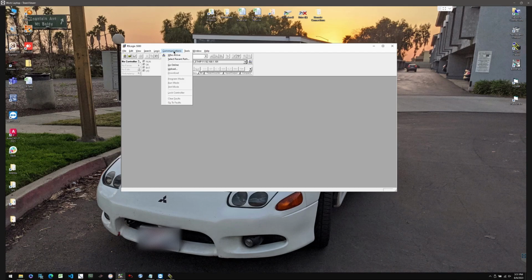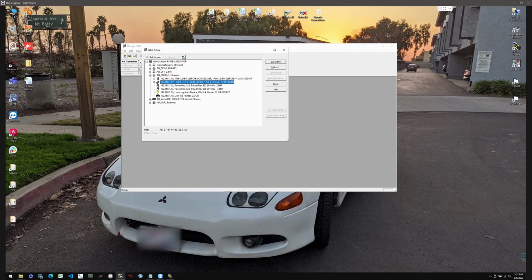So the next step is you want to go ahead and communicate with the PLC. We'll go here to communications and we'll go to who's active. We'll go right here, and again, this has already opened our Ethernet and it's already on our device here. So we're going to go ahead and select this device. Now, depending on the device, some older devices, how you're connecting to it, you may have to open this up and find the processor. But either way, on this style, on the L33s, this top section here is the processor as well, or you can go here, which is also the processor. It's the device that actually says the device name of the processor, the L33.